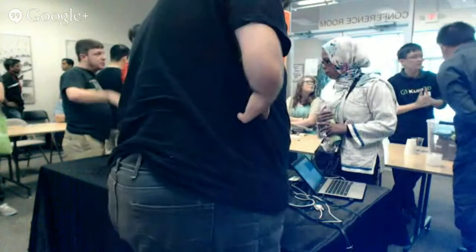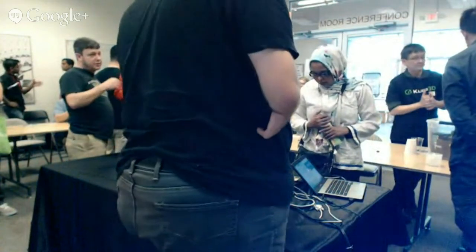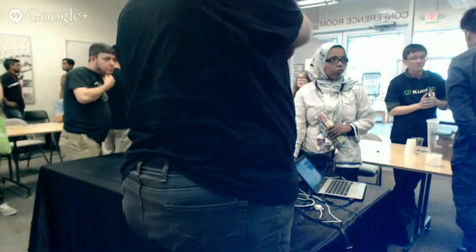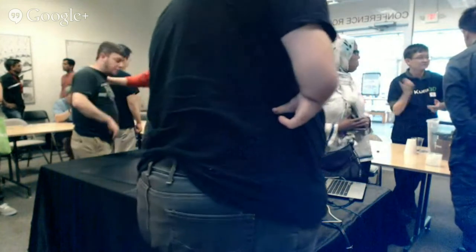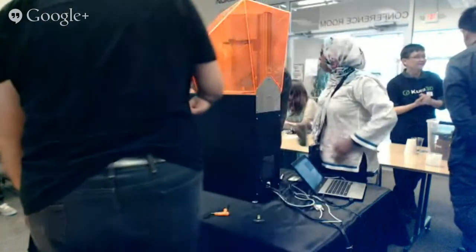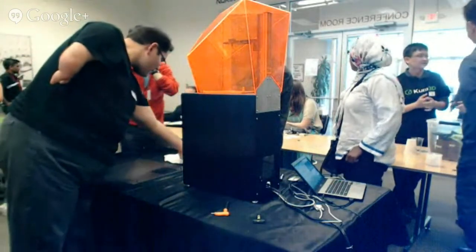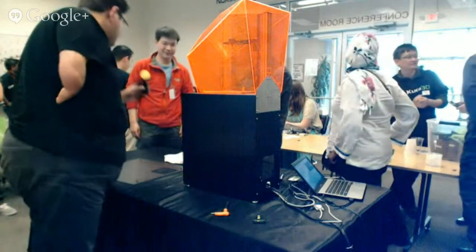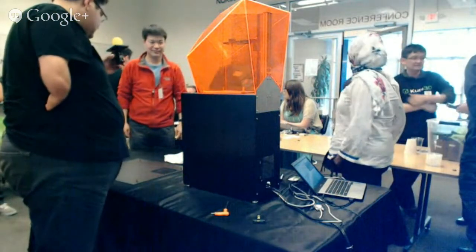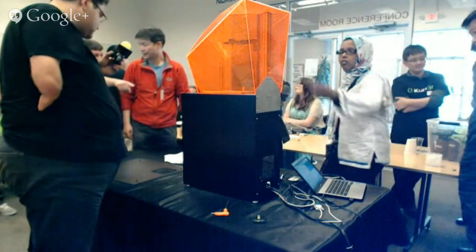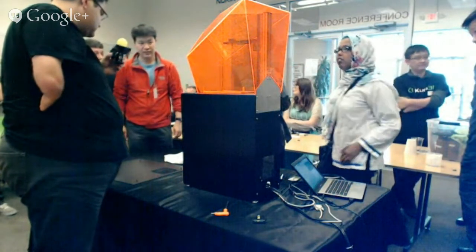But eventually, whenever you have a big change in surface area, there's always the risk that the change is big enough that you will either pull off the bed, the attachment point of this part that's sticking to the bed, or that you'll exceed the interlayer adhesion.